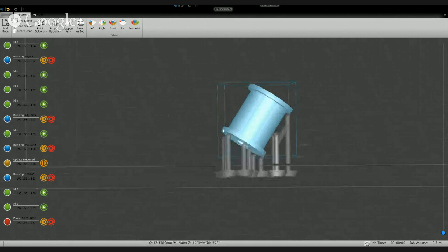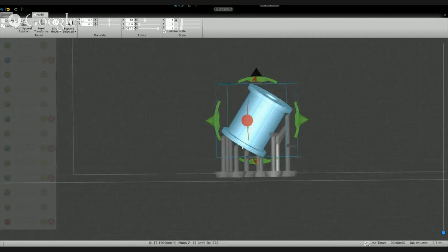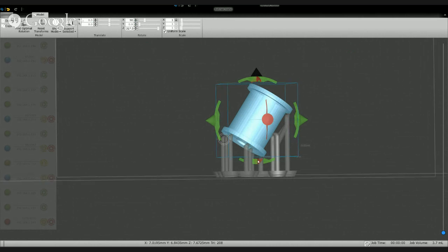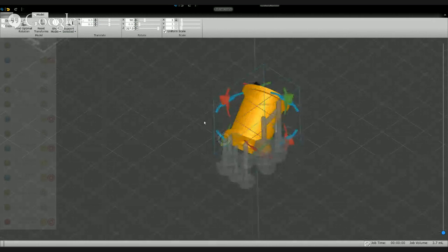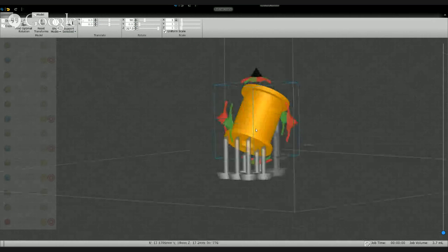And this, because it's angled at, what angle is that? About 32.5 degrees. It'll be fairly accurate. It won't dip. And the bottommost part and this overhanging part are supported. So if we do highlight unsupported features, it'll do an analysis, and none of the model is red. I'm not sure why it all came out yellow. That's interesting.